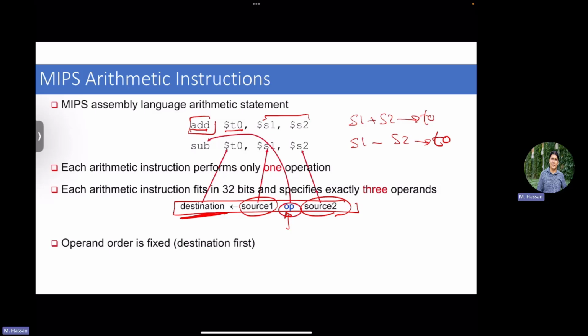Something that the ISA also defines as part of the contract. When I'm embedding this hardware, I need to know that if I receive those bits from the memory to my decode unit, I should be able to extract the fields. I should be able to extract that this is the opcode of the instruction and it means an add. I should be able to extract that this is the first operand, the second operand, and I should put the result in this result operand, right? To be able to extract this, you must have well-defined locations for your fields. Otherwise, the compiler will create the assembly by putting, for example, source 1 in a certain location, while the hardware will envision that the location is somewhere else, and it will bring the wrong number. So you break the contract. This is why the ISA defines how the instruction is created, but also where you should find different fields. If I go back here, the types we define.